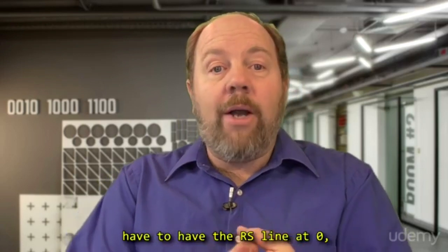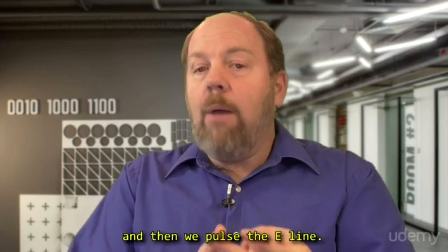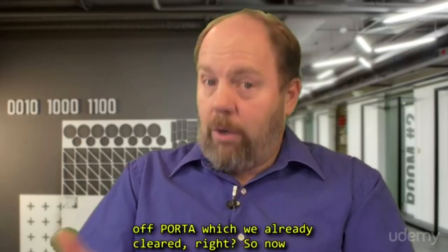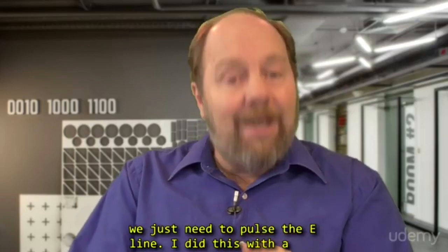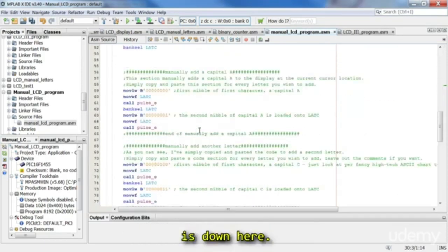We have to have the RS line at 0, which tells the LCD this is a command, and then we pulse the E line. Well, we've already got the RS line at 0. It's coming off port A, which we already cleared, right? So now we just need to pulse the E line. I did this with a short subroutine I called pulse E, which is down here.